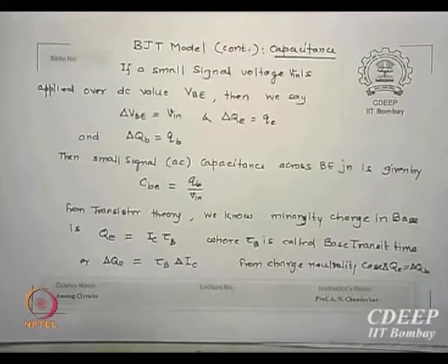But to make a point I have separated them, because in real physics, the base cannot increase the concentration of electrons in it because they must recombine, otherwise charge neutrality will be violated. Is that correct? So that term is valid here also, but just to make a point I am not changing it. So we define a capacitance related to the base emitter junction, given by the change in base charge divided by input voltage. Q is equal to CV.